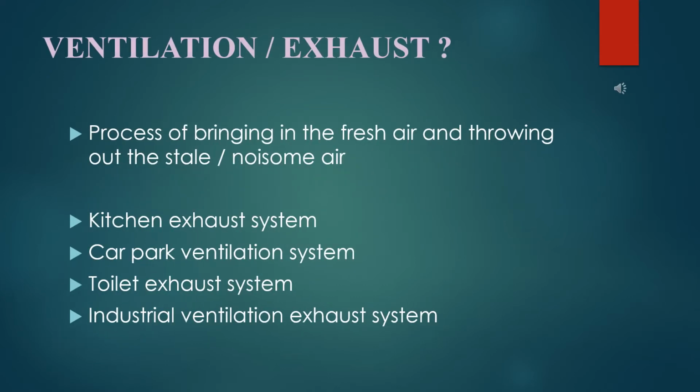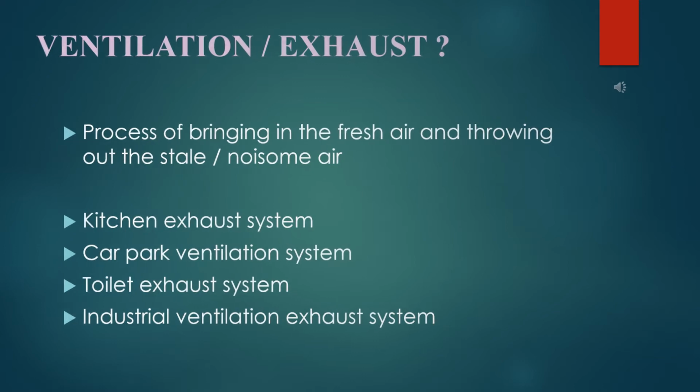Ventilation, exhaust. Ventilation is the process of removing the used unhygienic air and bringing in fresh air. Cold air has more density than hot air, so hot air will always have a tendency to go up. It helps the ventilation system to remove used hot air easily. Some examples are kitchen exhaust system, car parking ventilation system, toilet exhaust system, and industrial ventilation exhaust system.